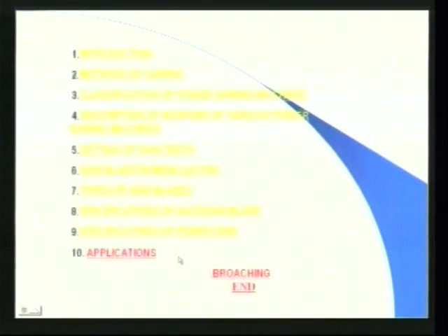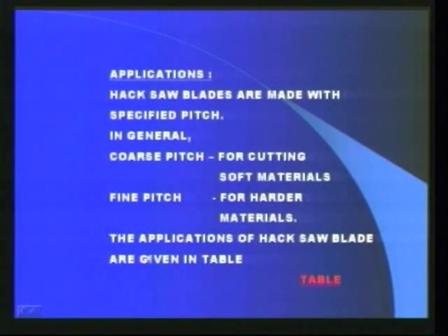Next we discuss about various applications of hacksaw. Hacksaw blades are made with specified pitch. The selection of pitch depends on the hardness, the shape and thickness of the material to be cut.